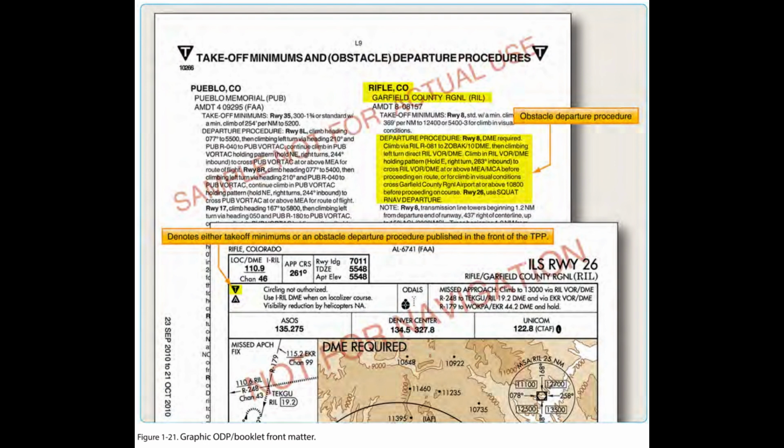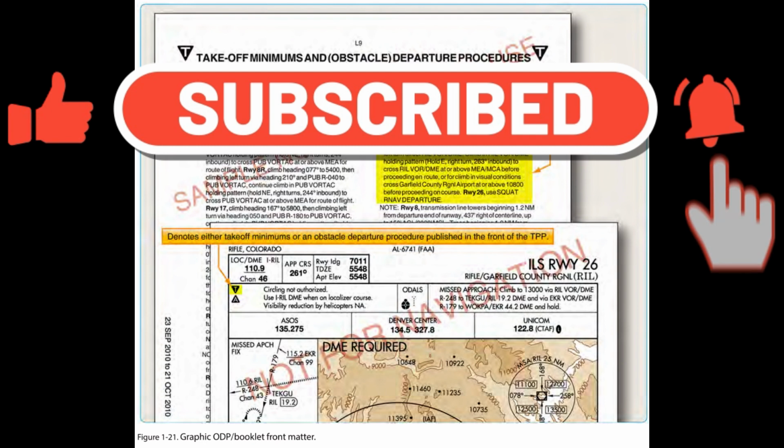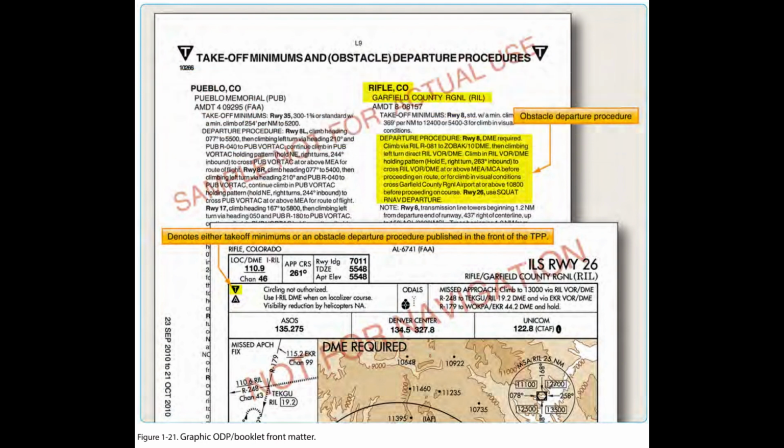Additionally, when close-in obstacles are noted in the takeoff minimums and obstacle departure procedures section, it may require the pilot to take action to avoid these obstacles. Consideration must be given to decreased climb performance from an inoperative engine or to the amount of runway used for takeoff. Aircraft requiring a short takeoff roll on a long runway may have little concern. On the other hand, airplanes that use most of the available runway for takeoff may not have the standard ROC when climbing at the normal 200 feet per nm. Another factor to consider is the possibility of an engine failure during takeoff and departure.